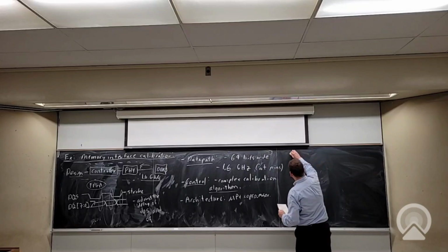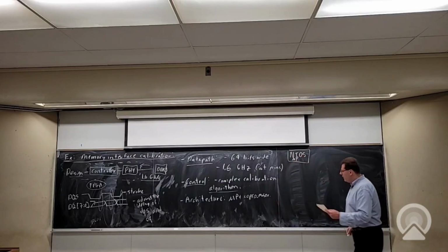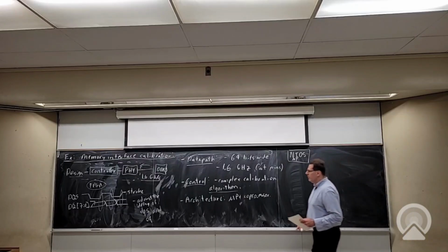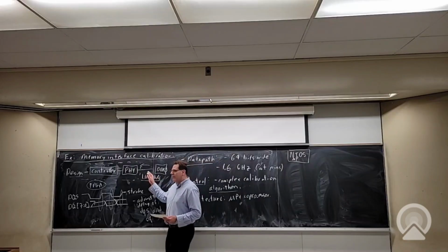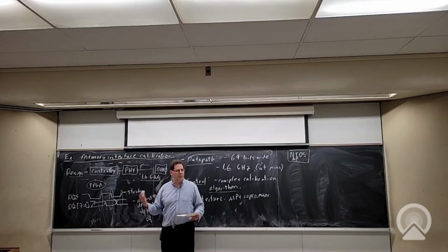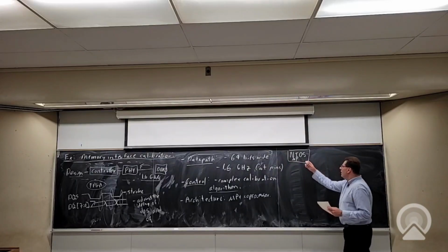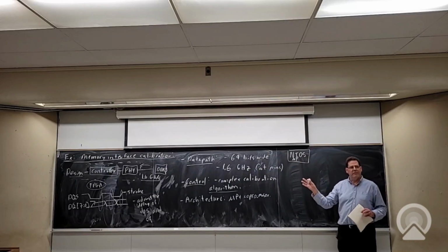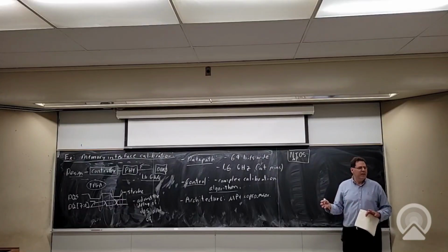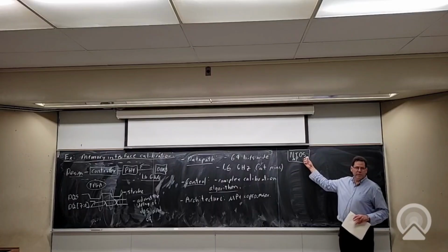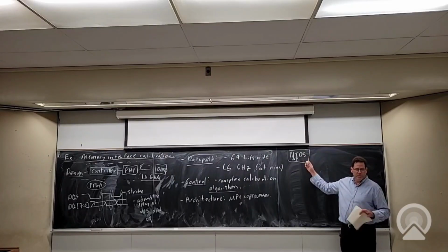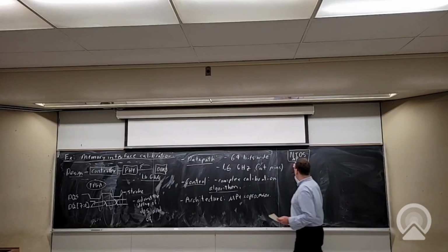So what we did is we used Nios, which is Altera's soft processor. It's a microprocessor made of soft logic. We don't actually need it to be that fast. Even if this calibration algorithm takes millions or hundreds of millions of clock cycles, that's still a fraction of a second, right? So that's fine. We can dial down its performance and make it smaller. So we use a very small version of Nios that only uses a few hundred lookup tables. So it's pretty small.